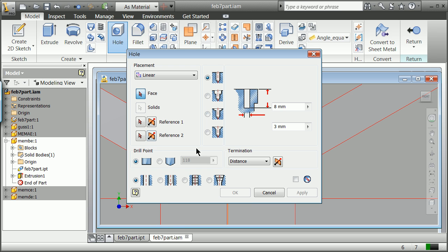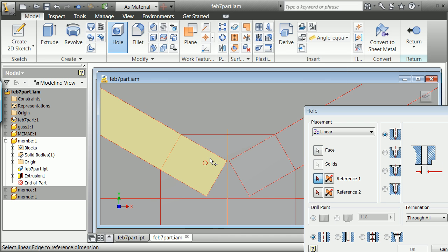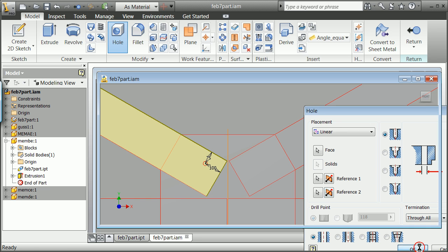Drill point. Generally we're going through, and I've made these all 25 millimeter in my example here. Grab the face, you've done that, tell it this face, grab the hole, and then your reference here is going to give you a distance. I'll make this 100, and if you think about where I placed that a second ago, it's going to be some odd calculations of sines and cosines to get these things to line up. Same thing here. Generally, we've been trying to keep those 3 inches away. That's very typical. 75 millimeter, and then I hit OK and apply.